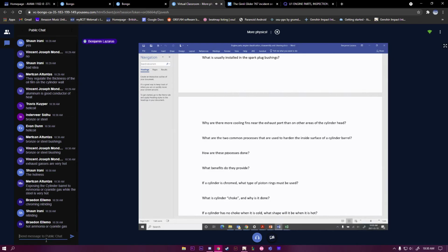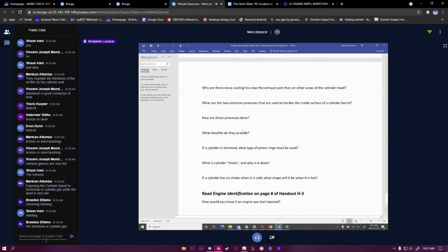Put it in the oven with hot ammonia or cyanide gas. Yeah, sounds deadly, and it is. Don't go in the oven. Well, it's 400 degrees or more. It is hot ammonia or hot cyanide gas. It would be deadly. Chrome plating, they use an electrochemical plating. They put it in a bath, they chrome plate it, and then at the last minute they reverse it to break the chrome plating and put a crack in it.